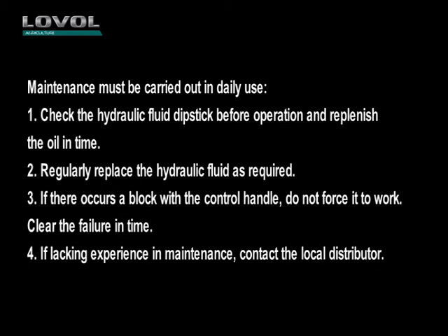Maintenance must be carried out in daily use. 1. Check the hydraulic fluid dipstick before operation and replenish the oil in time. 2. Regularly replace the hydraulic fluid as required. 3. If there occurs a block with the control handle, do not force it to work. Clear the failure in time. 4. If lacking experience in maintenance, contact the local distributor.